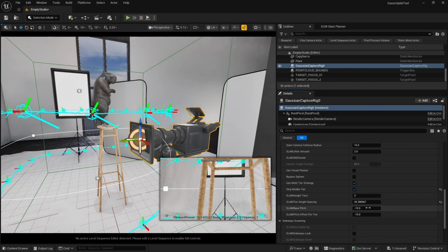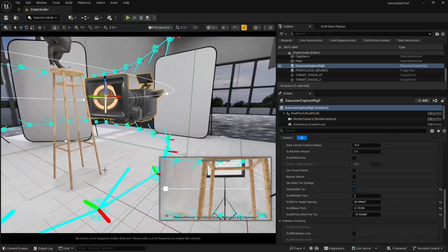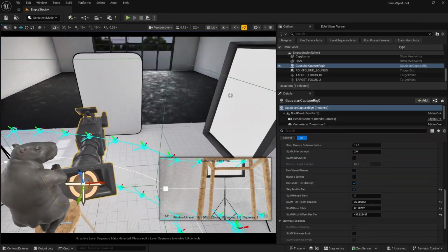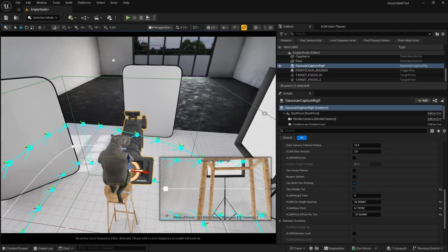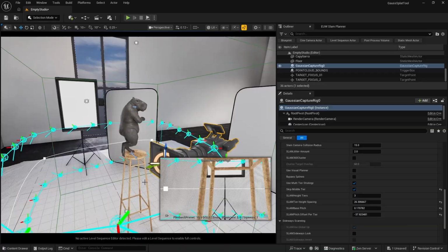And then we have these pitches. See, there's a base pitch, and then we have one for each one of the curves. Essentially when you're capturing objects like these, you want the nodes that are down here to have an upward pitch, and the ones that are higher to have a downward pitch, pointing down to make sure you capture the whole object. I'm just gonna turn them off, have them at 0, 0.